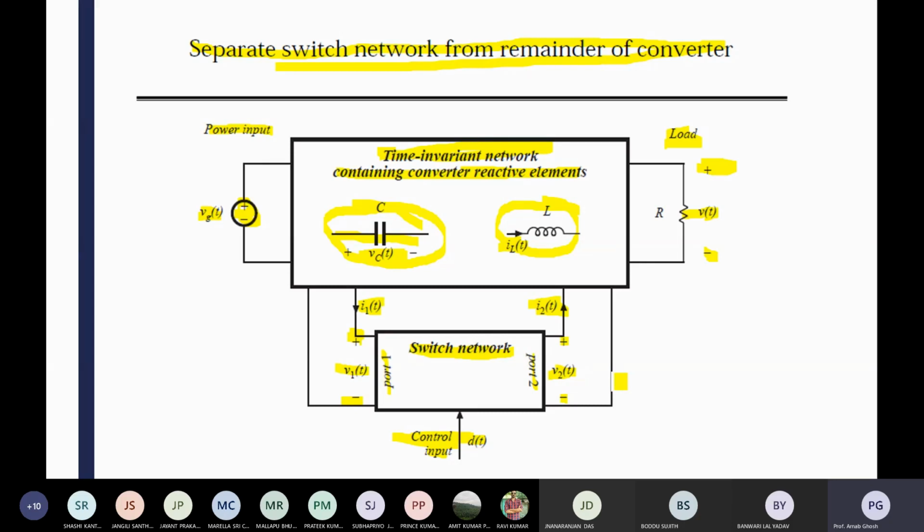In this case you do not need to write a script file or any code. You have to derive the transfer function of the controller, and for the rest of the things you can use the differential equations. In the case of the controller you can also use the differential equation, no problem. So what is the benefit of that last method? The benefit is that you are considering all the non-linearities without averaging. That is your separate switching network, called switch modeling.